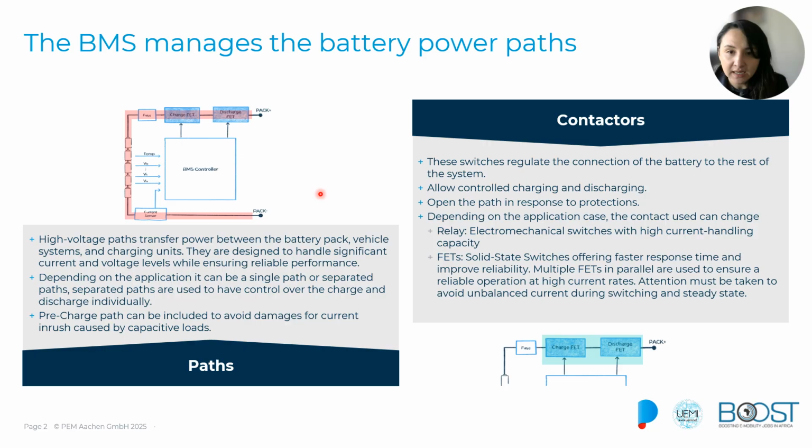The two main types of contactors that we have are the relays, or electromechanical switches, that have very high current handling capacity. These are durable and capable of operating with high currents, but they are also very slow, and they are subject to wear over time due to the mechanical parts that are moving inside of these relays.